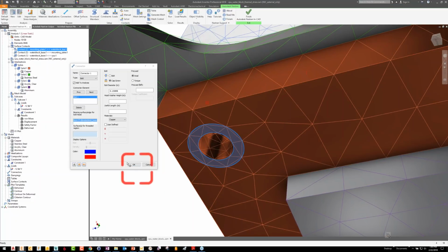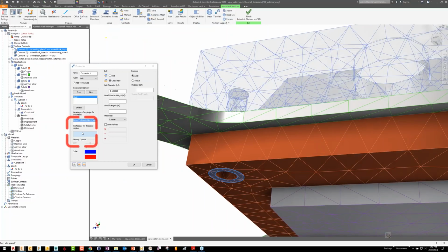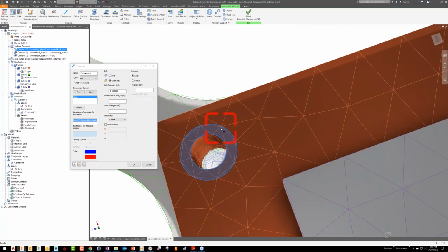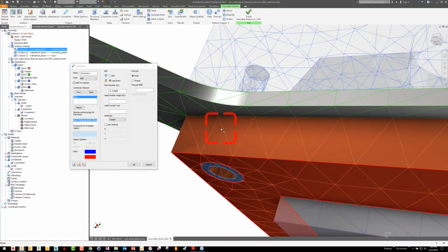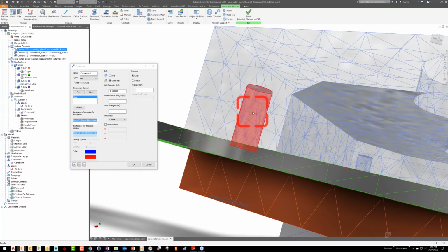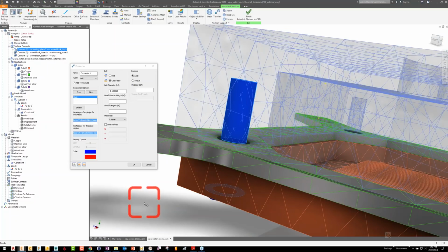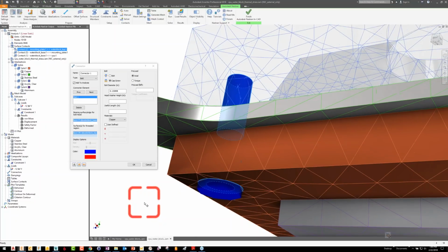Pick that face, and then it wants to know the surfaces for the threaded region. Where are the female screw threads? They're in this hole here, which I could get by looking down the hole itself, or by using Inventor's select other functionality here. Select the inside of the hole, and once that kind of minimal information has been plugged in, you'll start to get this.